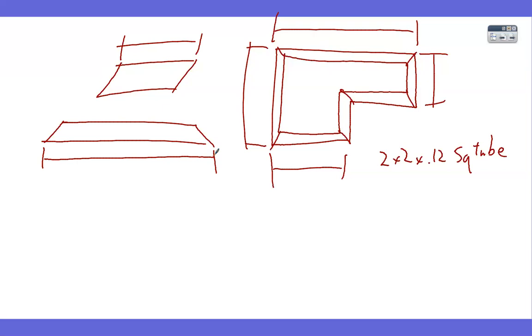And so I did a project like this. There was an almond tree shaker where the whole thing was square tube or rectangle tube, and a bunch of cuts like this at different angles. Some at 45 to make 90-degree cuts. Some at 22 and a half to make 45-degree cuts. Some at other angles. Some with one angle this way, one angle that way. Yeah, so lots of different cuts. And we actually made drawings to tell them how to cut each piece. We didn't just give them the assembly and say, hey, figure it out.